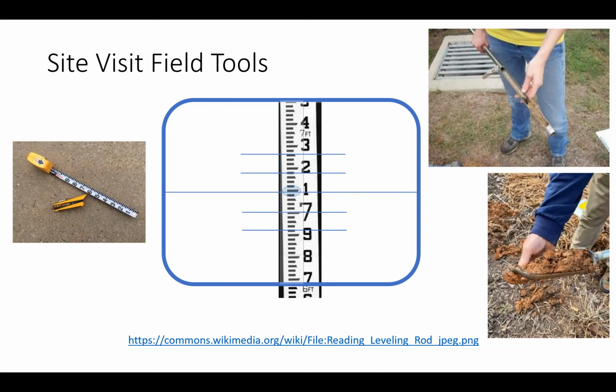I think it's helpful to kind of see what's going on. I also always recommend a soil test. But the auger is like a nice starting point. So Albemarle and Charlottesville, this area has a lot of clay-based soil. So it's a nice assessment to validate the soil map that we looked up. So like what is going on in the ground, what practices might be feasible based on what you're seeing. Yeah, exactly.